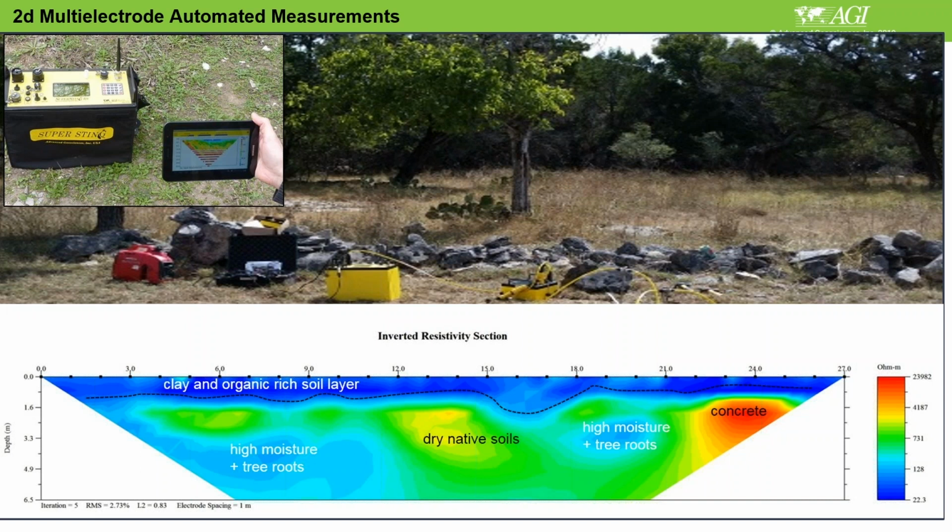In the borehole it is much easier in that case, because your current and voltage electrodes are in situ in the ground. So the spacing is also not much, because you keep the same spacing to get high-resolution information. That means your short normal, long normal, lateral log, all these have very, very close electrodes to each other, like a 16-inch, 64-inch separation. So you don't really need very high power output from the SuperSting.